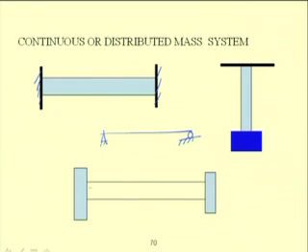So, one frequency will be the rigid body motion, as this is a semi-definite system. One can have a rigid body motion where the frequency is 0, and another motion where one can find the frequency by finding the node points. If one rotates the left side in one direction and the right side in the opposite direction, then one mode can be observed.